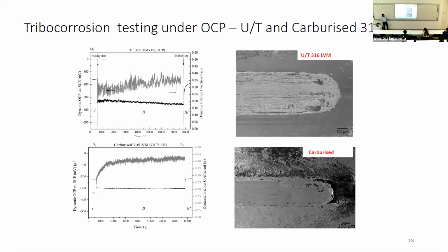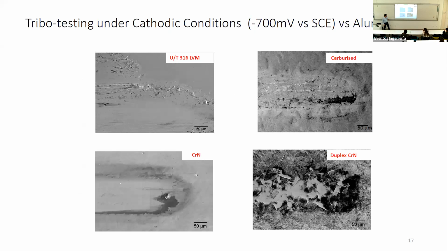How could that be happening? For the test under cathodic potential, if you look closely, it's not very clear here, but there are very fine micro cracks there. Those micro cracks will act as paths for the solution to enter and meet the interface. So if corrosion reactions are suppressed, that might not produce much of a problem.